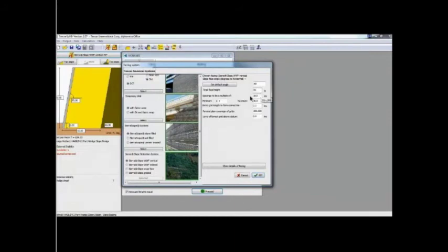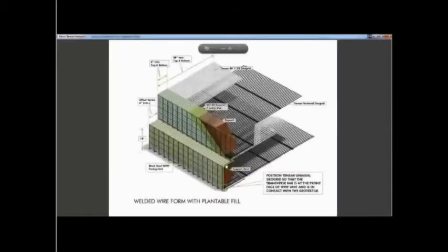So we will leave the default spacings at 18 inches, but we can have a minimum of 1 times 18 inches. That means the Geogrid will fall at the bottom of every basket, but we can allow the Geogrid to span up to 2 baskets, so we can have up to 36-inch spacing between Geogrid layers. We will use 100% plan coverage of Geogrids, so we will not use percent coverage, although we could. And then the level of the lowest grid above the datum, above the toe of the structure. Let's leave that at 0 inches so all of our Geogrid layers line up with the bottom legs of the baskets. Now I'm going to click on Show Details of Facing to show what we are designing specifically.